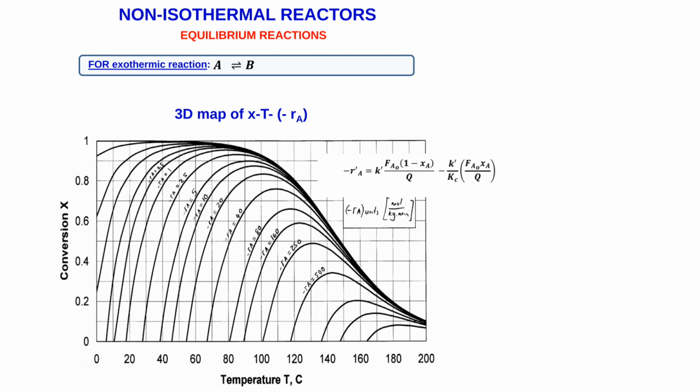So what is going on in this beautiful figure over here? Still for our example system, we have the equilibrium conversion line shown here, where the rate goes to 0. What is now also populated on this figure are some iso rate lines, so lines where the combination of concentration and temperature is such that as I follow the line, I will achieve the same rate. So per illustration, at 10% conversion and a temperature of 120, I can achieve a rate of 500 moles per kilogram per minute.